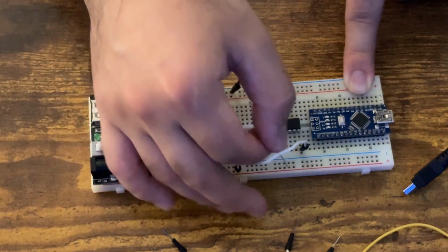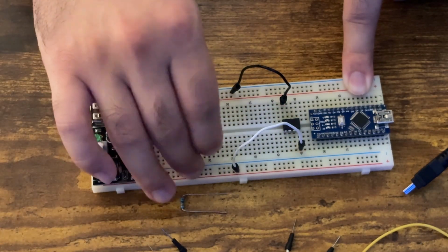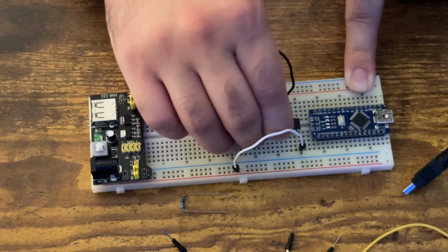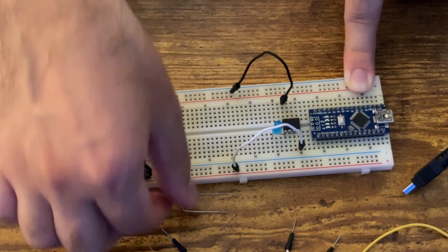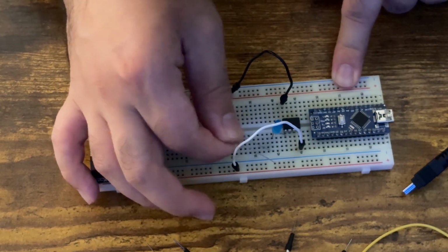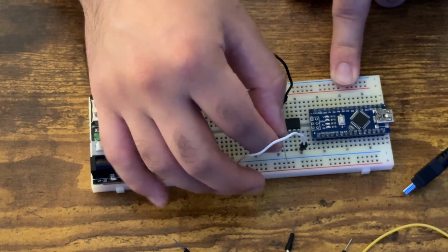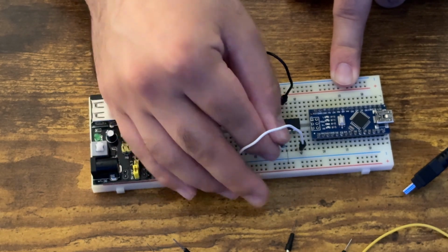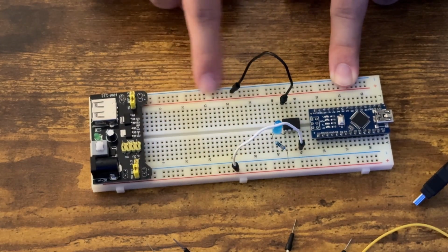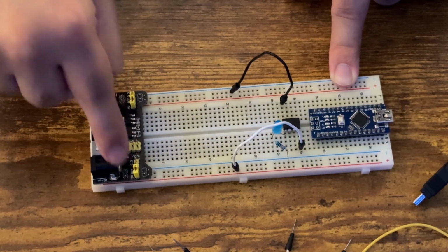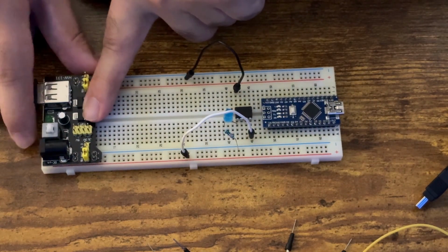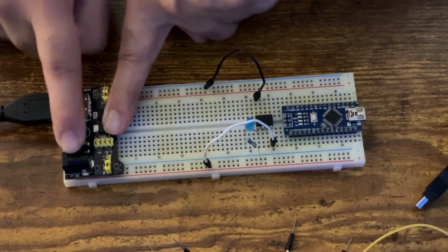Okay, and we need to connect our LED. So remember, it was physical pin 5, which is PB0. We connect the longest leg of the LED, or positive side, anode, and the negative side goes through a 330 ohm resistor to ground, or minus. And these things are connected together because we have them on both sides. Okay, so I've connected to my laptop. Let's see actually if it works. Turn on.